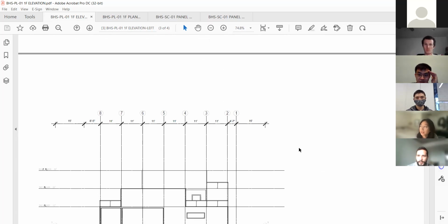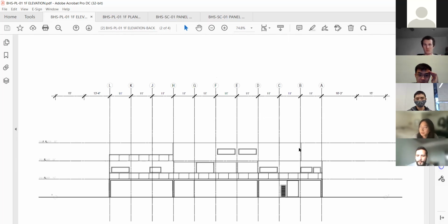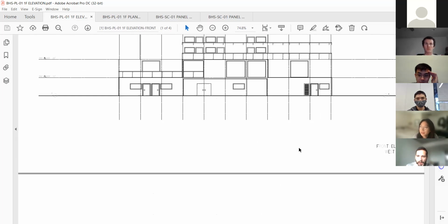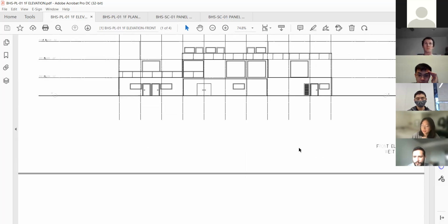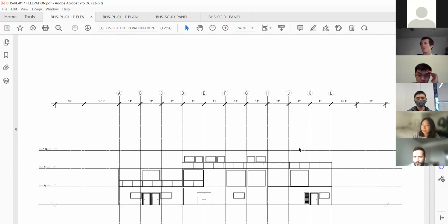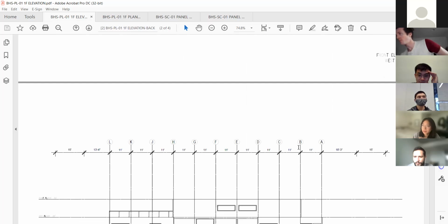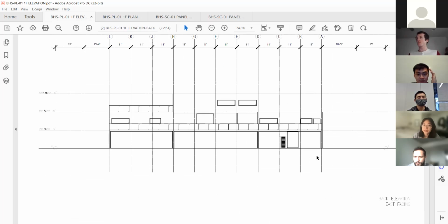The sloping is very small. It could separate the roof into several squares, and within each square there's a slope, like a roof drain. That's clear. You don't have to slope the entire roof. Normally in Brazil, we would have like 0.5%, at most 1%, so just keep the number in mind.